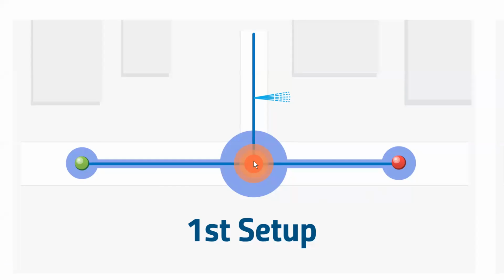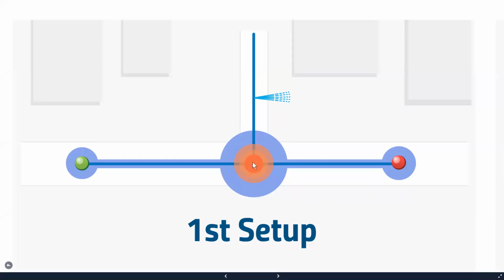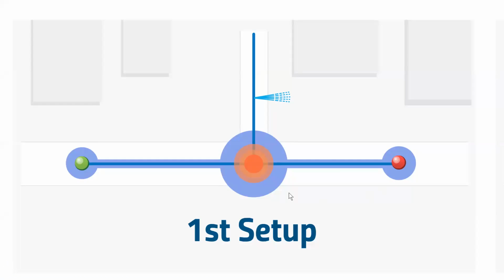The processor is sensing that, is reading that sound. It is a common sound. You're getting the peak. And the mathematical equation puts the source of the leak right here on the pipe. However, as a leak detector, a smart leak detector would do, recognize that you're on a T or even an intersection and not quite be happy yet with the accuracy of that leak.